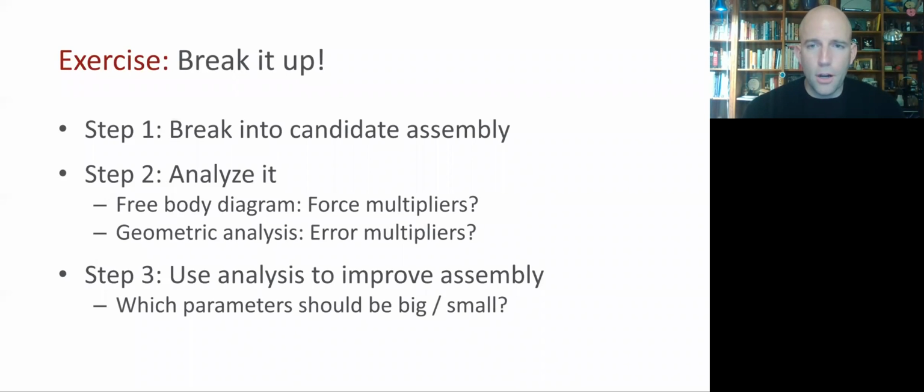And the first 2 are break it up exercises. So what we're going to do is look at a single component and say you're forced to break it into an assembly of multiple components. And you can imagine a reason for this, like you want to use a cheaper manufacturing process or something like that, or you need it to be disassemblable for portability, or in order for it to be able to fit together some other components that must be separate.